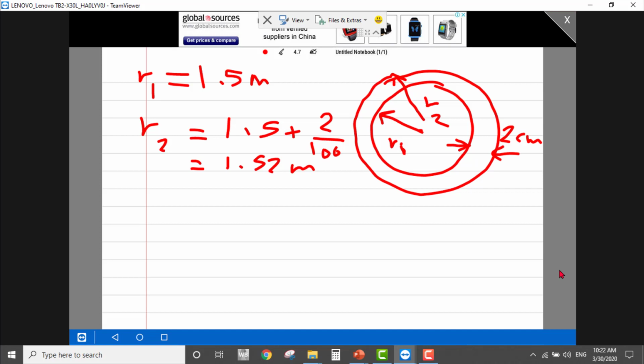Now regarding the resistance network, because sometimes in the statement of a problem they ask us to draw the resistance network. So outside we have convection and we have radiation. So I'll draw both. And once we have both, we'll have them in parallel. So this is R convection, and here we have R radiation. Then we have another resistance for the stainless steel, for the shell.